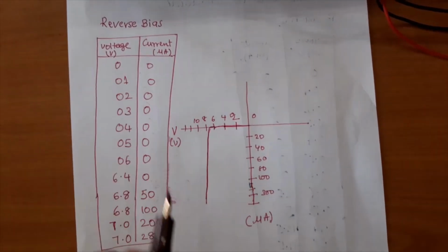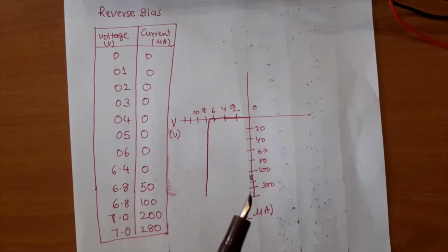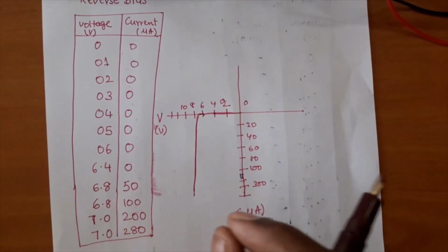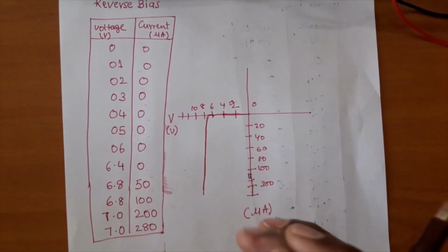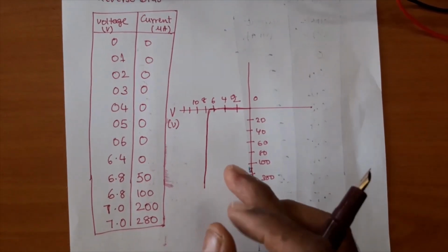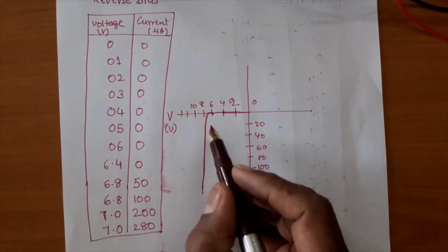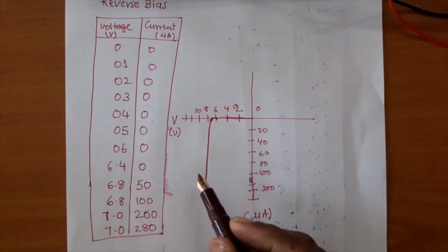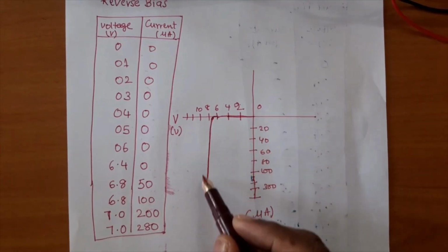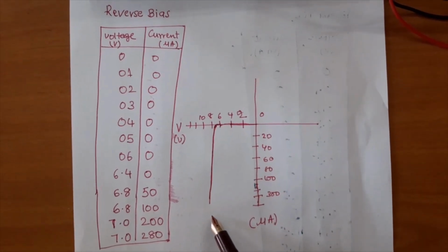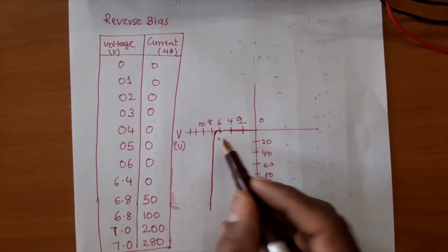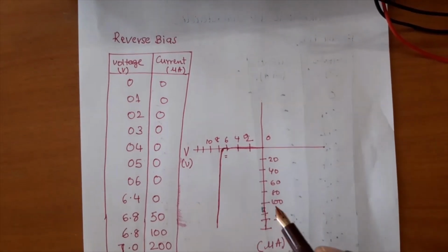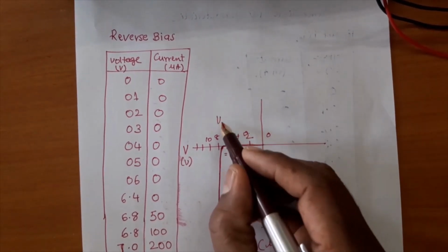In the beginning of the video we have seen that the major difference between a junction diode and a Zener diode is the doping concentration levels. And the second most practical application is that there is a sharp breakdown in reverse bias wherein the current sharply and suddenly increases once you reach a certain voltage. The certain voltage is now called the Zener breakdown voltage Vz.